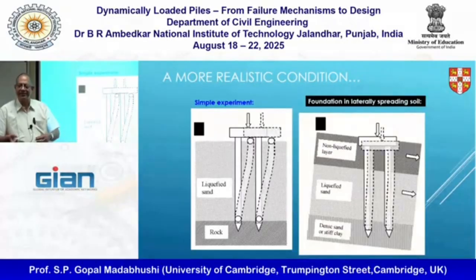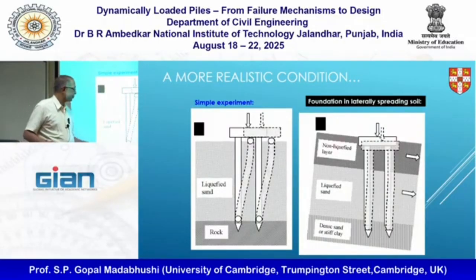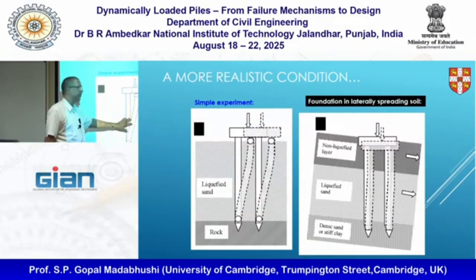They'll check for the buckling load. If it is coming anything like 2 or 3 times the load the column is going to carry, they'll get scared, and they'll start designing horizontal struts to support the columns. So, a quick check, to make sure that doesn't happen.